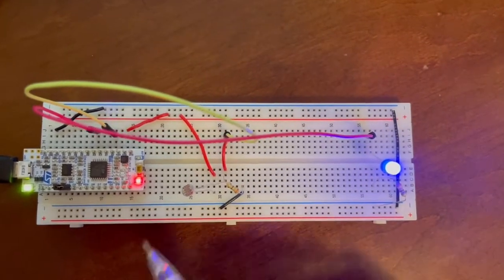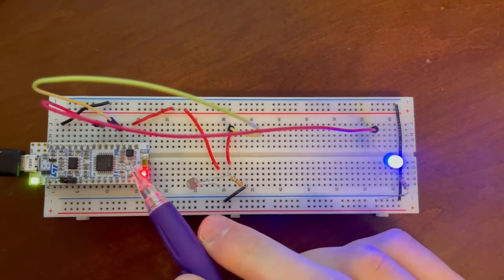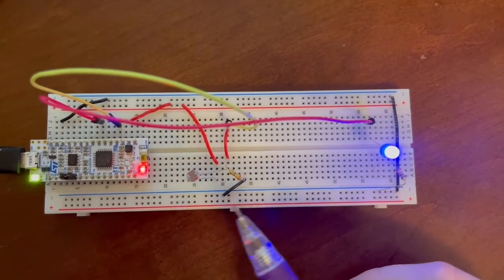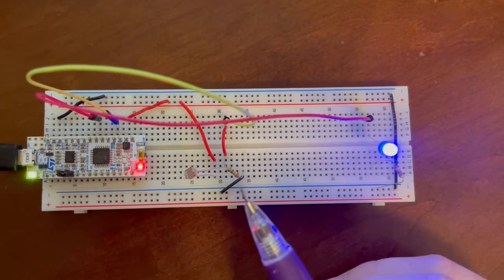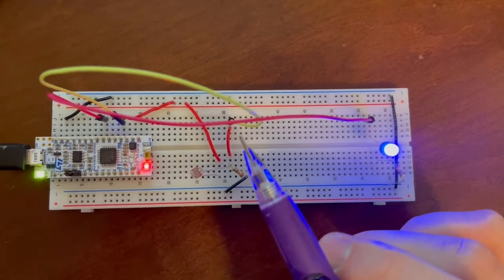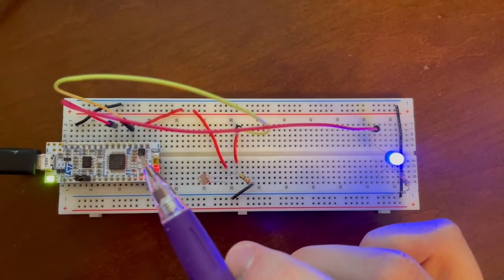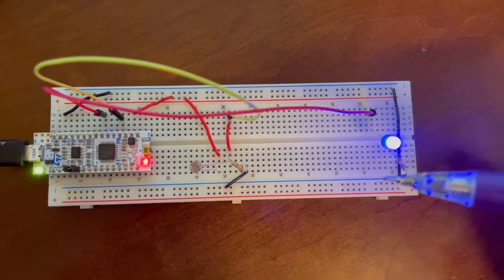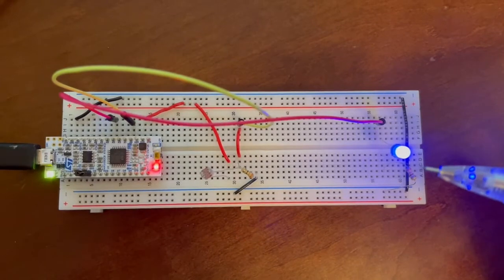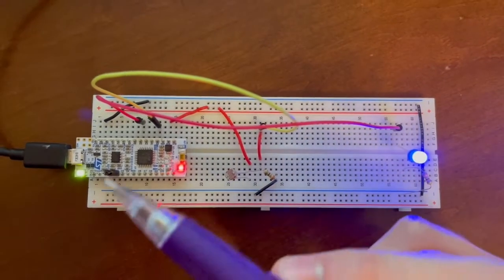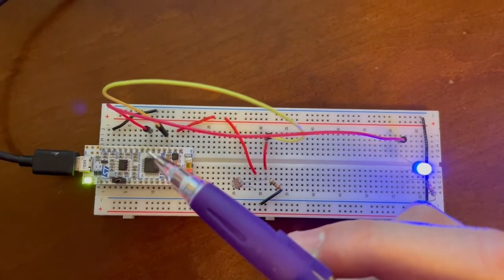As you can tell, my microcontroller, my Nucleo board, is providing a 3.3 V power supply to my photoresistor and this 330 ohm resistor connected in series. These form a voltage divider, which will be used as the input voltage to my microcontroller at the A0 pin. As you can also see in this circuit, I have a simple LED circuit over here where an LED is connected in series with a 330 ohm resistor, powered by the analog output pin of my microcontroller, the A3 pin.